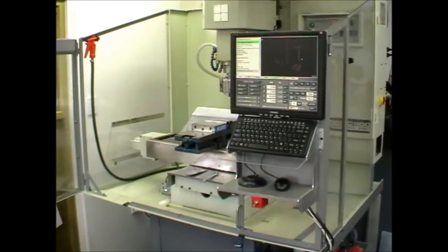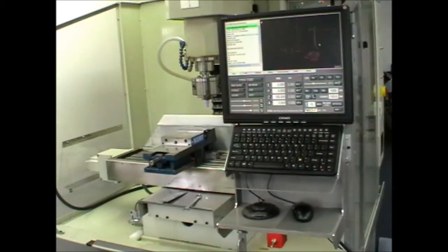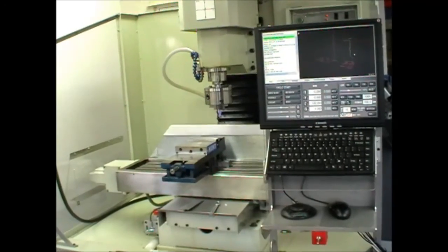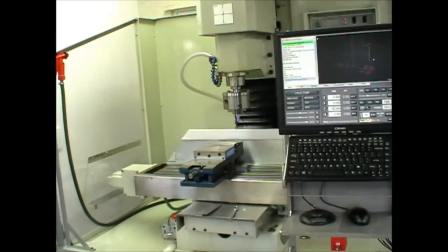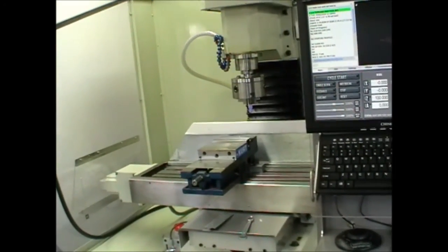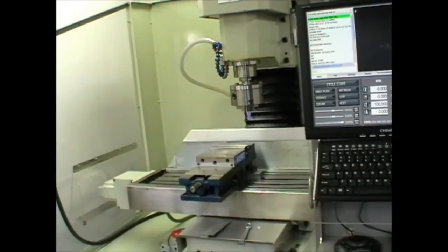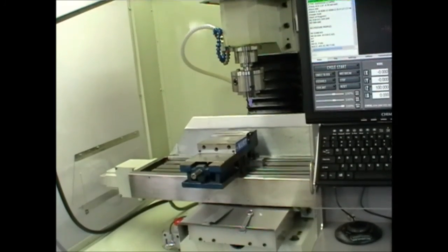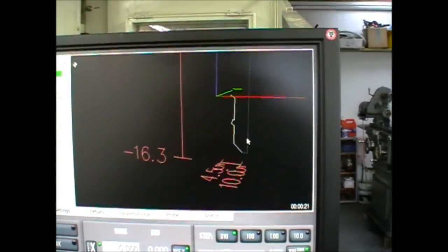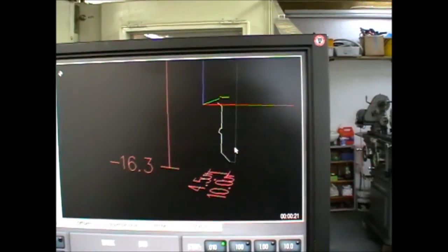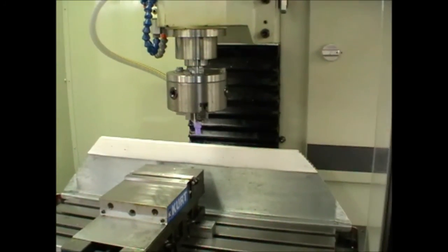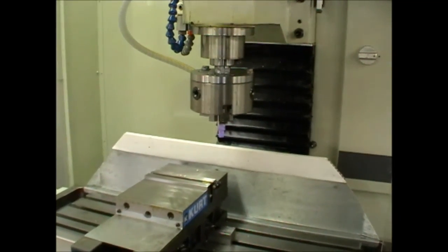Okay, well let's start this video a little bit towards the end of the journey so you can get a feel for where it's headed. We're going to do some spindle turning, but not just normal Z X moves to turn face and diameter, but also we're going to turn radii or arcs and angles or chamfers. So here's a back plot of the NC code showing some angles and radii, and here's a little piece of sample acetyl to try it.